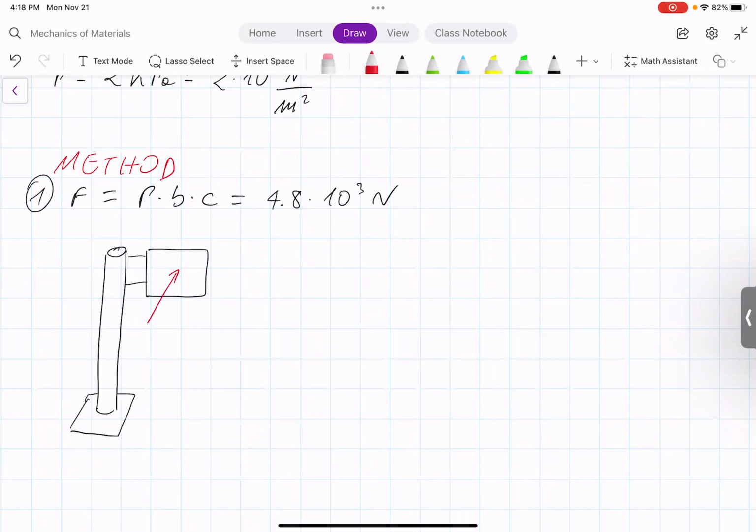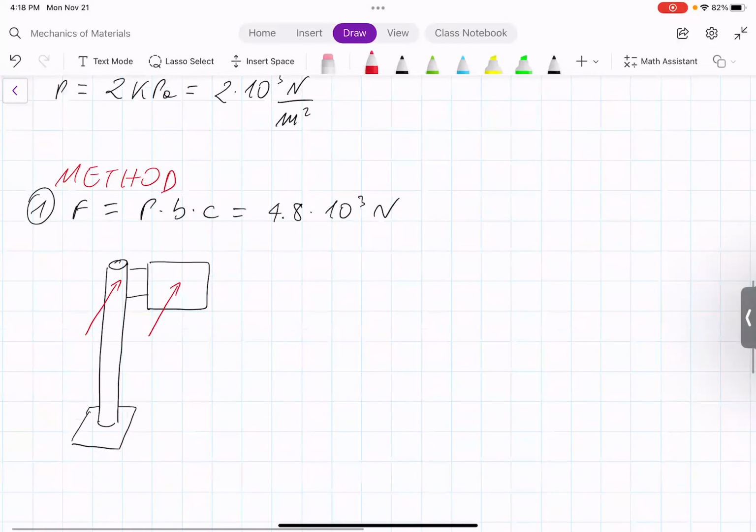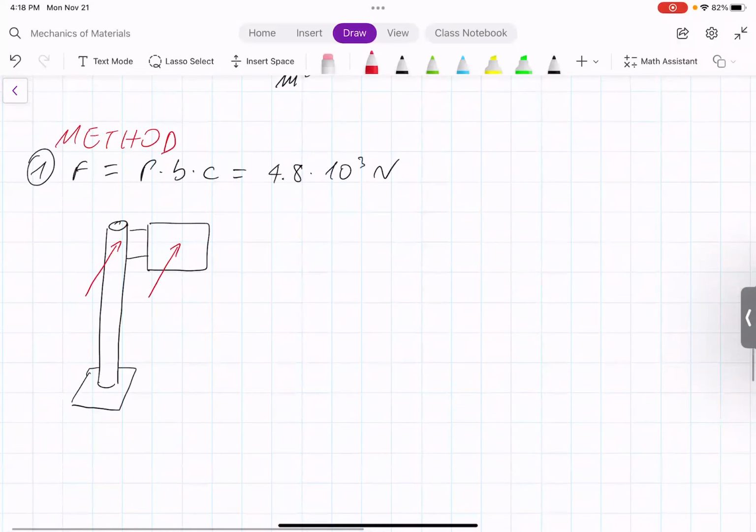We move the force in this direction here, and it means that if we move the load in this direction, we add a moment, and the moment is about the vertical axis. We call the vertical axis axis Z. So in this case, we will have a moment Mz. Since we moved the load and we added the moment, we can remove the original load.